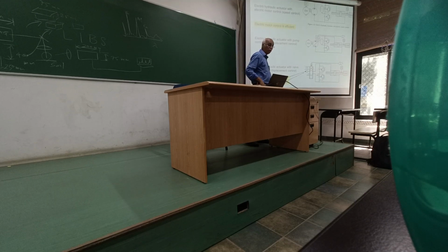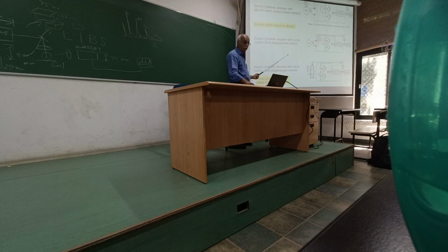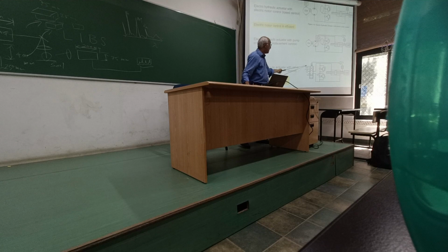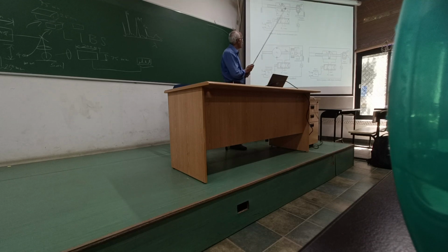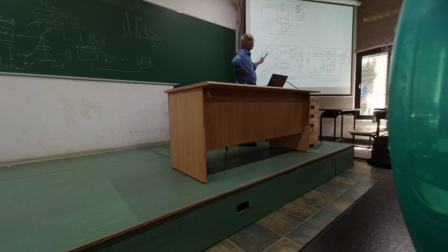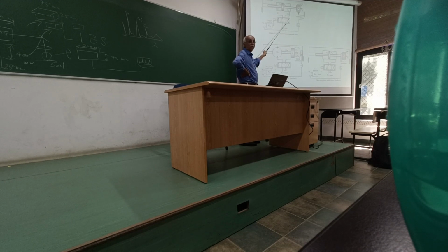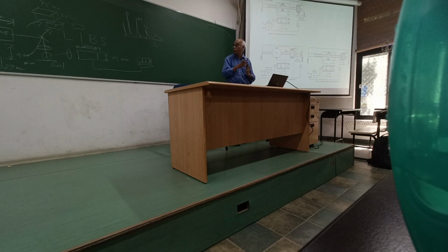Okay. And so this type of directional control valve approach, controlling this is very easy, and it's being adopted in the majority of the trucks. So how do we control the directional control valve? We use something different. See, if you see this valve, it looks similar, of course, a 4x3 valve, but it has two parallel lines over here.